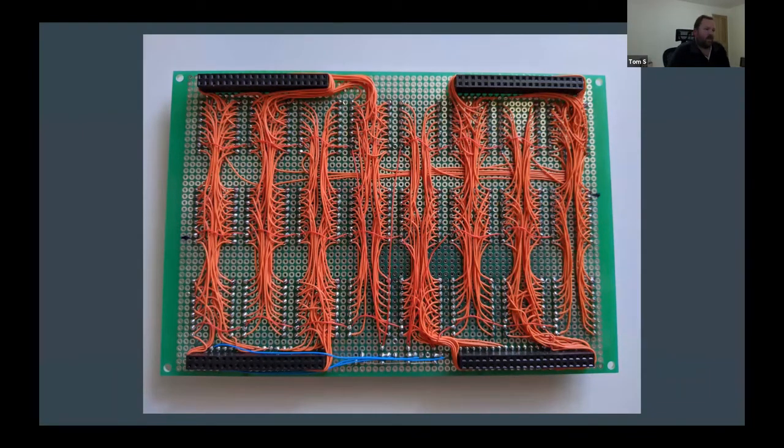A couple of small changes have been made to the backside of this board. You might just barely be able to see that there's some thin red wires mixed in amongst all of the orange wires, and they're the power supply for each of the rows. But I did notice that as the display was being filled up with characters, you could see it getting dimmer and dimmer. And I guess 30 gauge wire is not that great at carrying lots of current. So I modified that to use some thicker wire, and that helped that situation a bit.